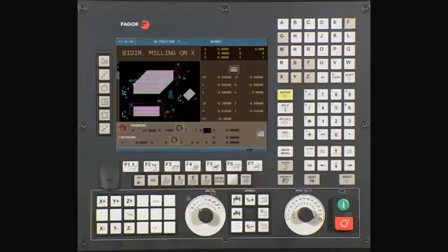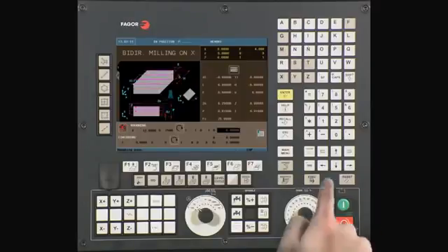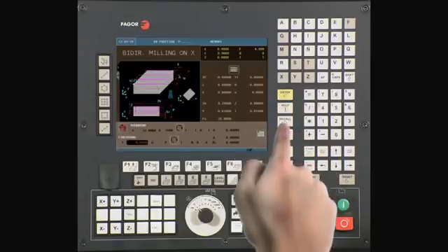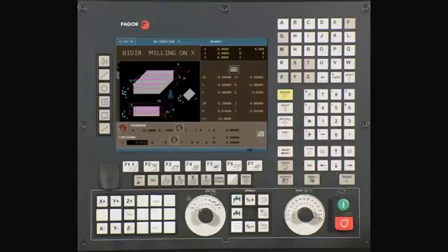D. Enter your tool's offset number. In this example, we are using offset 1. Type 1 and press Enter to continue. Next is your milling step over field. To ensure clean cuts, type in a value less than the diameter of your selected tool. In this example, we are using 0.8 inches. Type 0.8 and press Enter to continue. In this example, we will not define a finish operation. It will be necessary to set the finish tool number and offset to 0 to skip this operation.